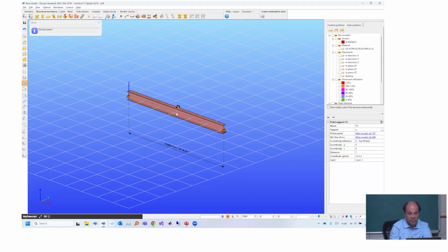We click the positioning points of the load. And then again, I could click anything else here on the left or right, but if I just want to move by 1 meter, I can also do that. I press the X key on the keyboard in order to make this field active, and I can type here 1000. So that means that from the actual position, with the relative offsetting using the coordinate system, I can say to move the point from the selected towards 1000 in the x direction. And I press enter and the load is supported.